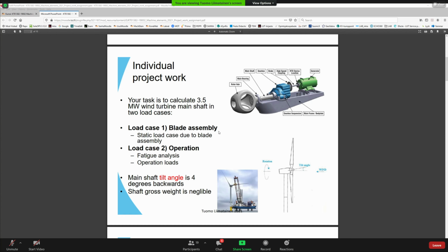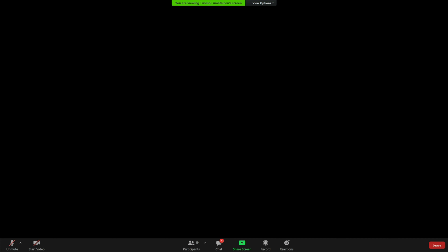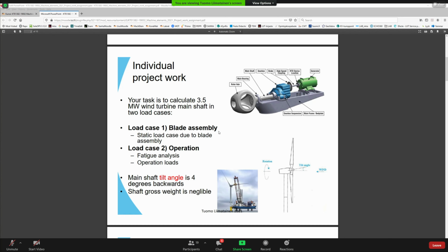Well, that is exactly the reason that we are using the Goodman. Because the Goodman equation transforms our mean stress plus amplitude such that we can compare it to the Wöhler curve, which has been drawn for only amplitude. So the Goodman equation is used for that purpose. You are right about that.